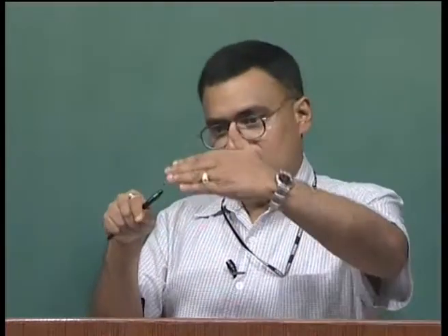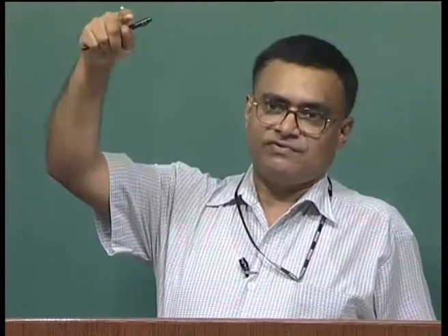So we could write down the balance between y3 and x2. Now we are in the stripping section, so we have to begin with the stripping line equations. So we are trying to substitute xt in terms of y1 from the total condenser, then y1 to x1, x1 to y2, etc., till we have one more equation between xt and xw. Then we make an overall material balance or species balance. We'll have 2 unknowns and 2 equations.